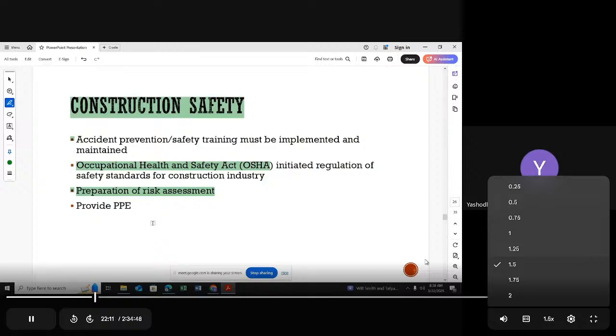There were some voids in the slab, open spaces in the slab. If there is any void in the slab, definitely we have to cover it with some rail or something like that, because when we are walking on the slab, sometimes within a very short time period we can't see it. So we have to cover it. On that site, people did not cover those voids correctly or perfectly.